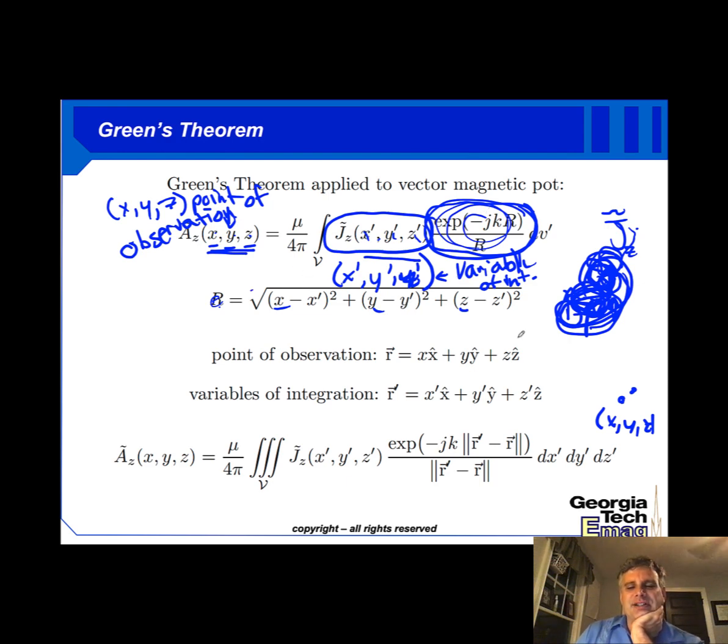And that's because really this is a six-dimensional problem. If I have a radiating system with J sub z, and I need to calculate a field map, I basically have to digitize the universe and sample it, and every sample point results in another integration of this body that itself must be sampled. So we're almost looking at a six-dimensional problem.